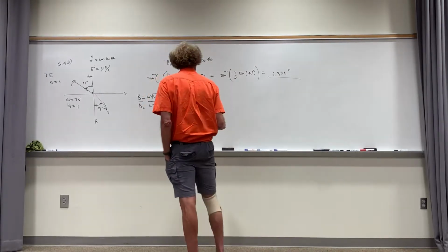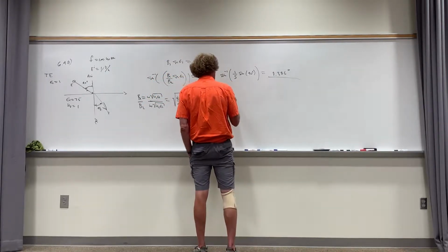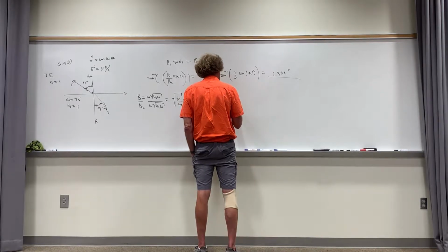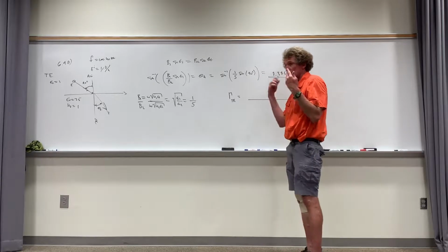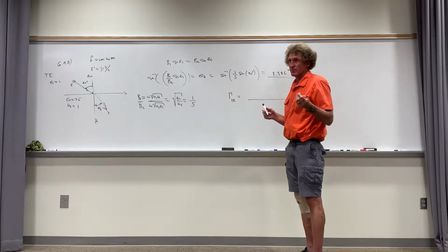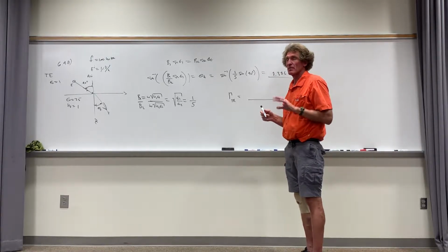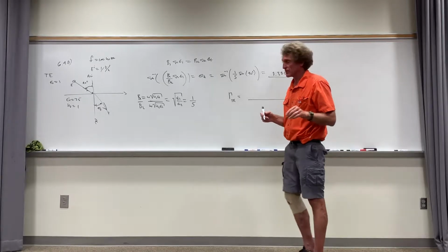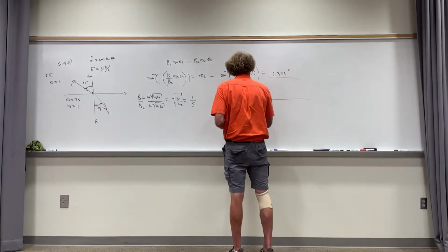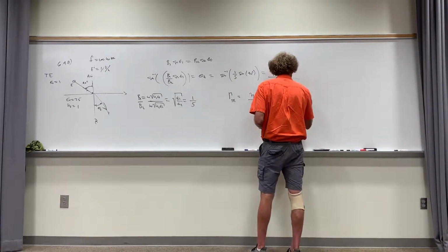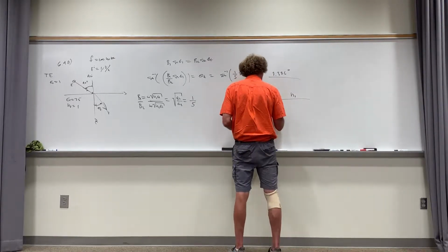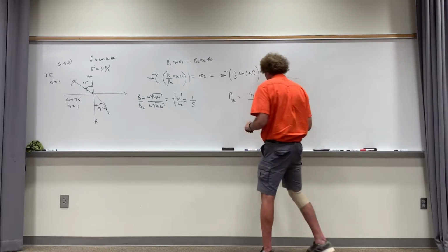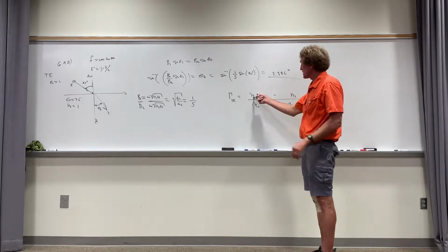Next thing we need is the reflection coefficient. All right, this is the reflection coefficient for TE. Now, I always tell you, if you need a little mental trick that helps you remember this: I know I'm always going to have eta 2 and eta 1 here, and there's a subtraction sign. I'm always going to have eta 2 and a plus sign here, and eta 1 here. Correct, class? It's always the media I'm going into.